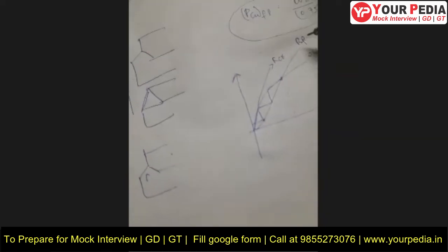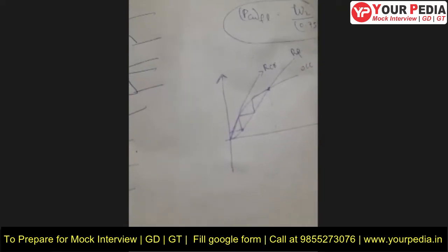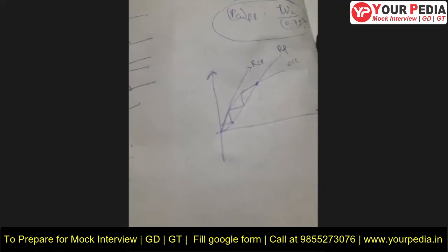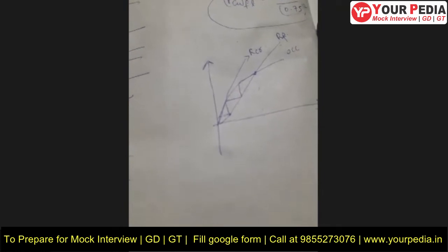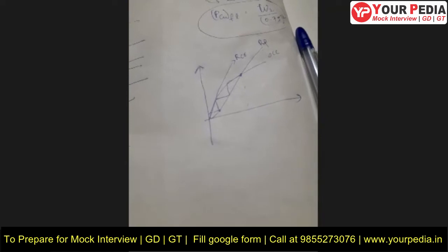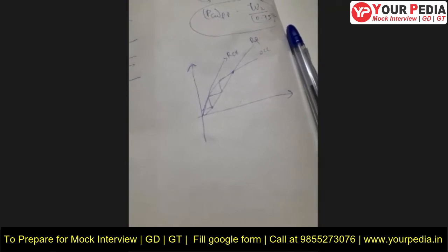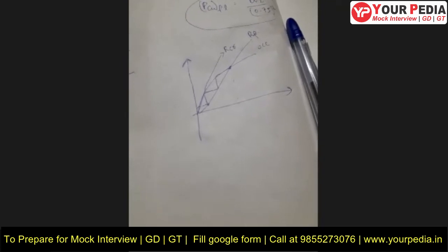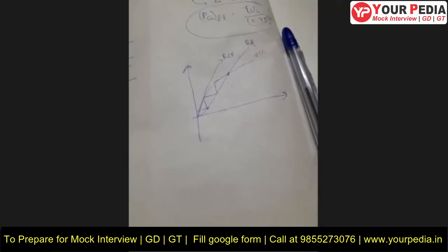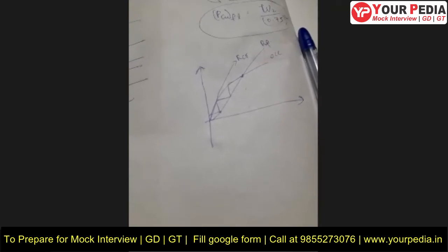Okay. What are the methods of reducing the armature reaction? Sir, mostly we use interpoles and compensating windings. From a structural point of view, we employ chamfered poles to reduce armature reaction, sir.